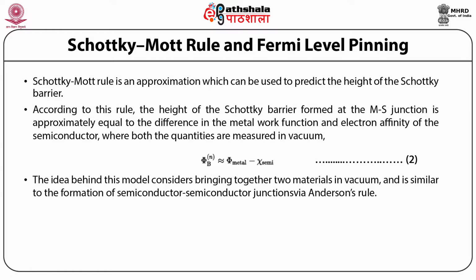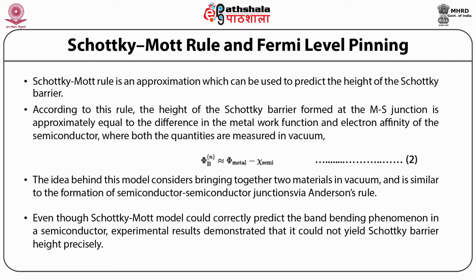The idea behind this model considers bringing together two materials in vacuum and is similar to the formation of semiconductor junctions via Anderson's rule. The Schottky-Mott rule is obeyed by different semiconductors to varying degrees. Even though the Schottky-Mott model could correctly predict the band bending phenomena in semiconductors, experimental results demonstrate that it could not yield the Schottky barrier height precisely.